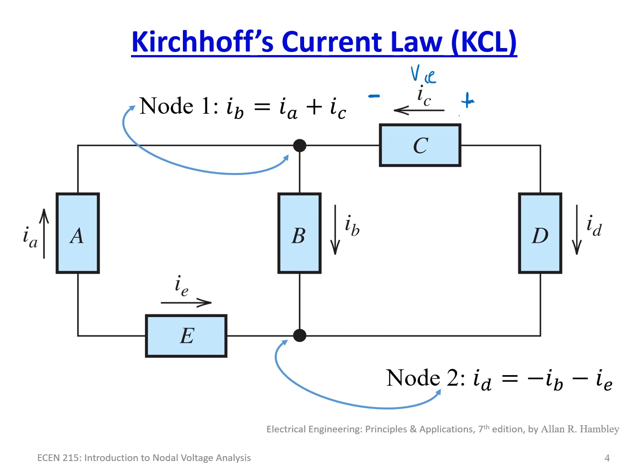Okay, what is VC? So VC is equal to IC, and we're just going to assume these for the moment are resistors. So this is RC. Well, correspondingly, we know IC is equal to VC over RC. So we can solve for IC in terms of the voltages of the elements. And we're going to use this in nodal voltage circuit analysis.